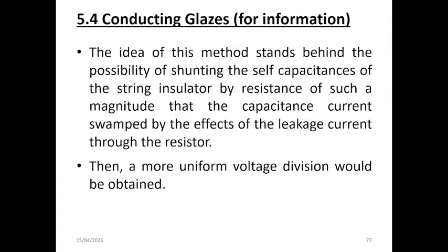So the idea is to apply a semi-conducting glass on the surface of the insulators, which introduces a controlled leakage resistance along the string. And this resistance effectively shunts the self-capacitance of each unit, and it can reduce the impact of them.